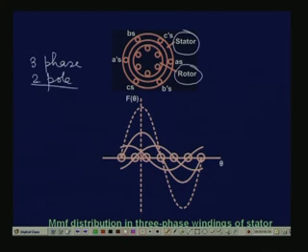You see that, for simplicity, for each phase we have drawn one coil. This is one set of coils A and A dashed, whose axis is like this. When you pass current through this, it produces flux, and the flux passes through all sides. This is called the air gap flux. So the net flux will have an axis, and this is the axis for the AA dashed coil.